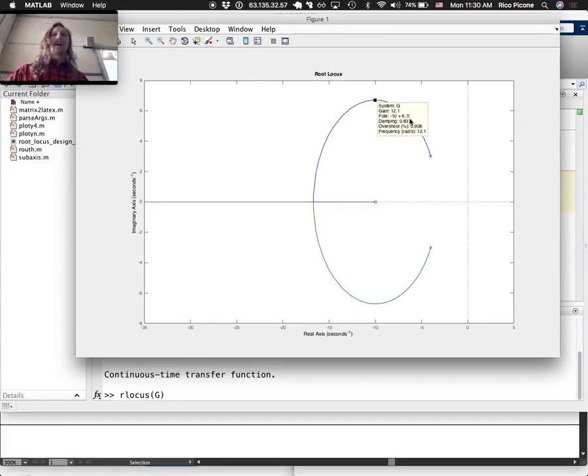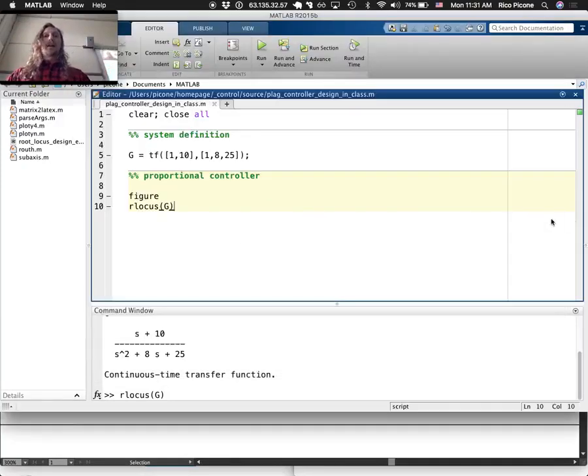So that is our gain that we would associate with the transient response that we desire. So let's call it our K1, and it equals 12.1. When I did this last night, I got 12. So there's a slight variation every time you do it. Okay, 12.1 is our gain.